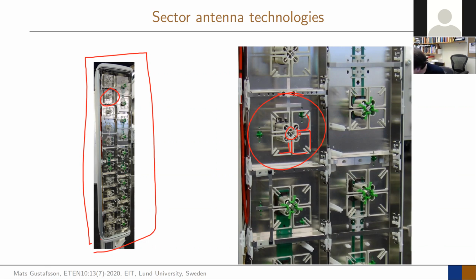If you see these ones, they actually don't all have the same size of antenna elements. So there are quite a lot of antenna elements that sit there. But the majority of the structure is long in this direction and fairly narrow in these ones, which means that the pattern is very much controlled in elevation. So you can direct your beam, for example, downwards.